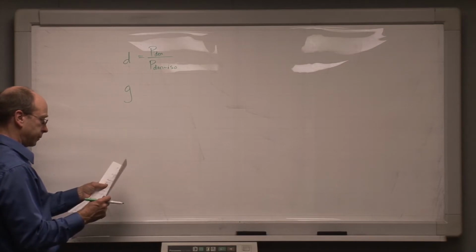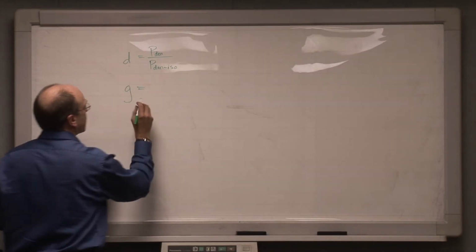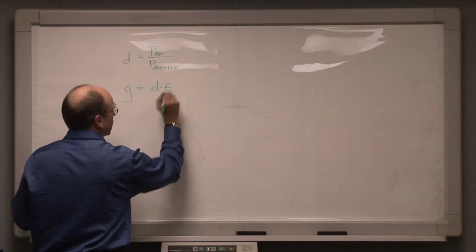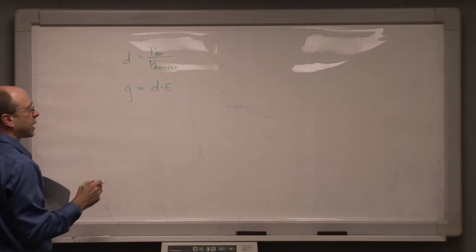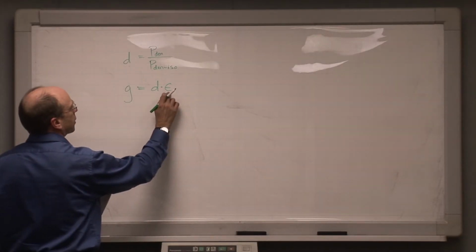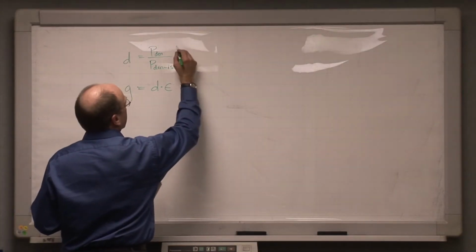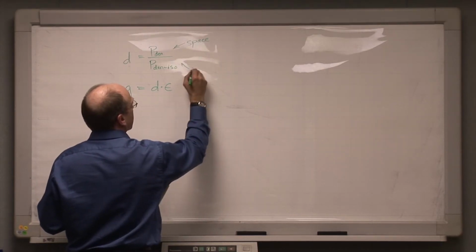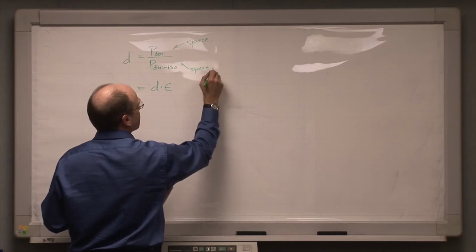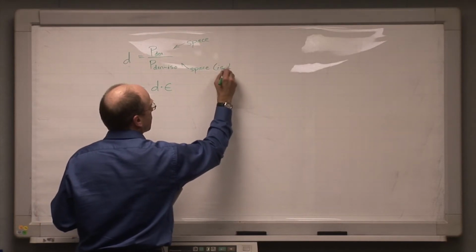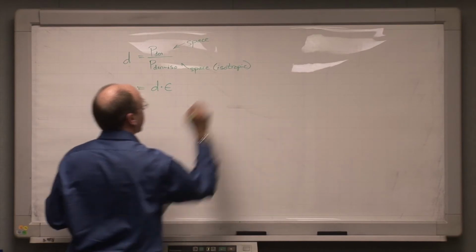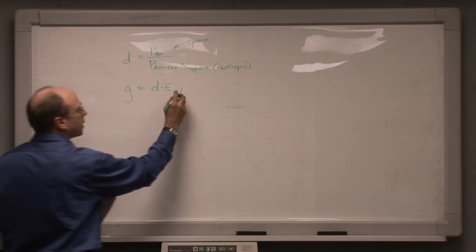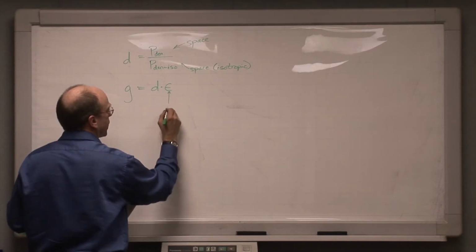Now, gain is equal to the directivity of an antenna multiplied by the actual electrical efficiency of the antenna in terms of energy that's coupled from a circuit. This is dependent entirely on energy in space divided by the energy that would have occurred in space due to an isotropic radiation pattern. Gain is directivity multiplied by whatever the efficiency of the antenna is in terms of coupling energy in and out of a circuit.